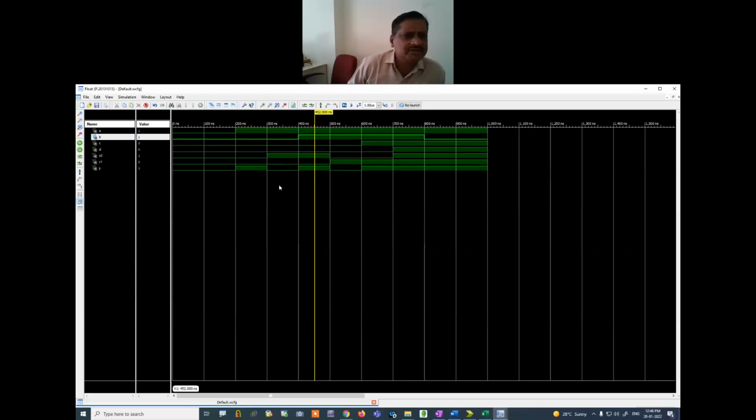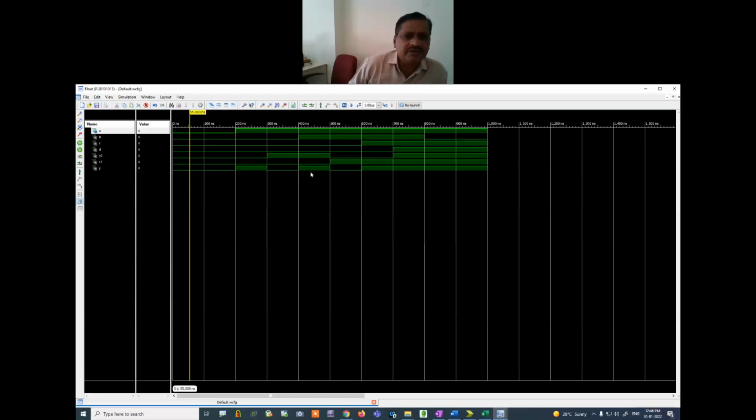To the next slot. If we come to the next slot, look at this two, 1 0. What is S? S is 1 0. If S is 1 0, in that particular case, 1 0 means C. What should be the C? The value of C will remain the same. Sorry, this is not 1 0. This is 0 1 again, because S0 is the LSB and S1 is the MSB. For 0 1, the value of A will be copied. Now look at what is the value of A. The value of A here is 1, so this value will also be 1.